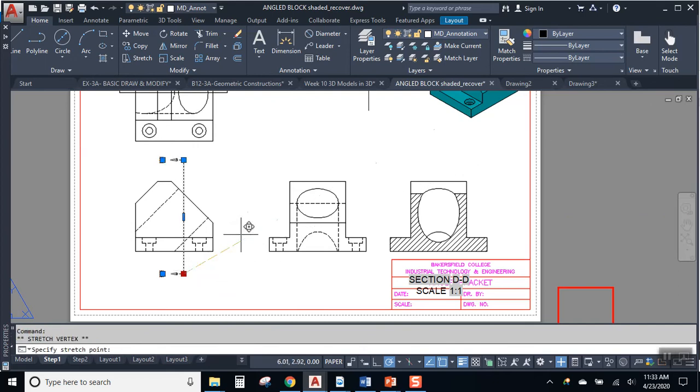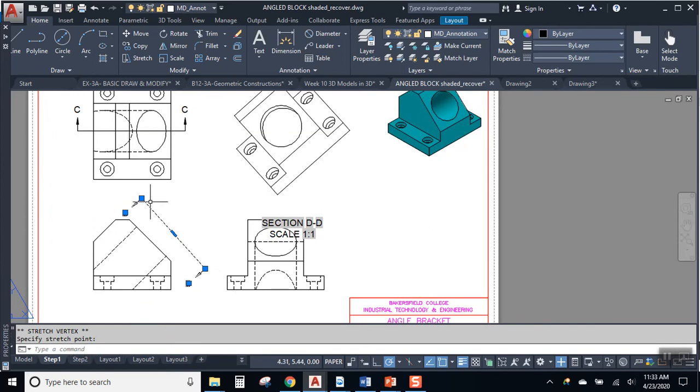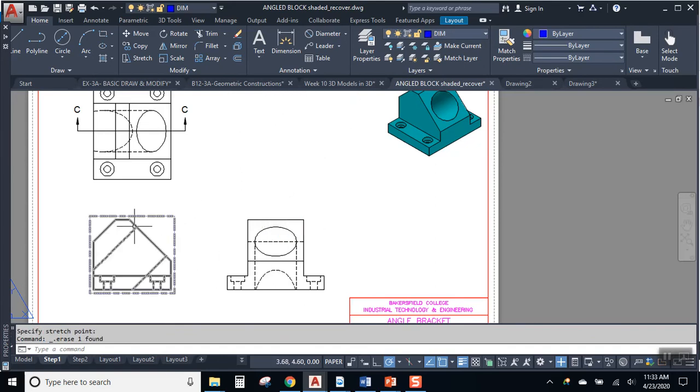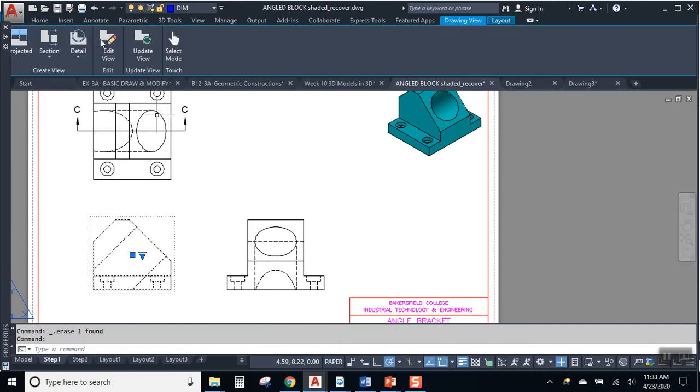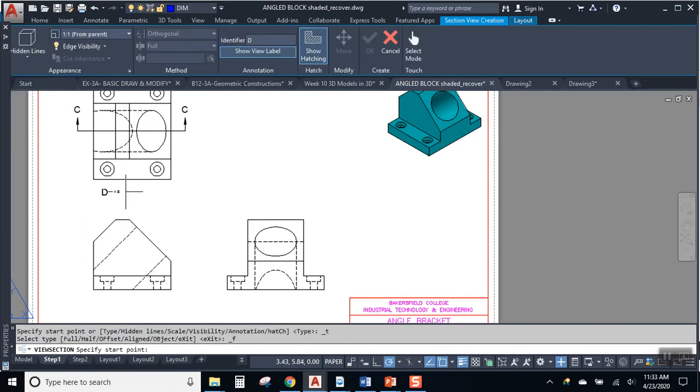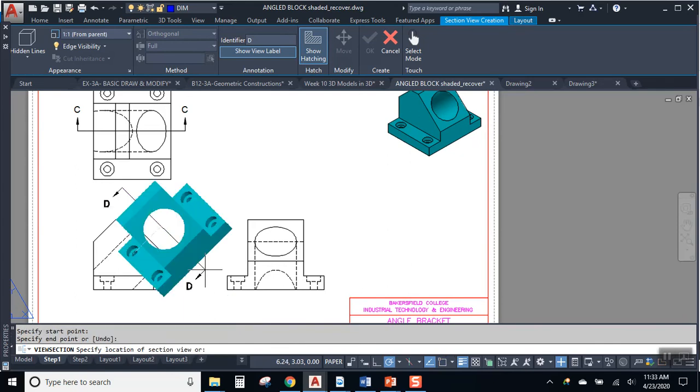What if you took a cutting plane and you didn't cut through the object, but just pointed at the object? Do you see what I'm getting at? Yeah, so here's the basic idea. This is a 45-degree angle, right? So we're going to set our polar to 45. We're going to pick our front view. We're going to set up a full section, but we're not going to cut through anything. We're just going to draw a cutting plane line out in space.